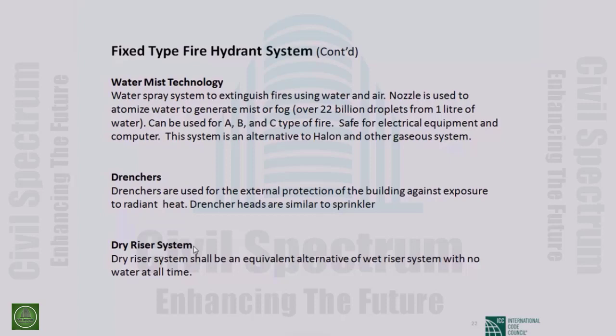So if you can keep it dry, then the pipe will last longer, the life of the system will be longer, but there will be a time gap to start and finish. So if you can properly handle it, a dry system can work, and it is very good for longer life, very long life. Normally, a hydrant system does not last very long. Within 10 or 15 years, you can see most of the valves and the engine parts are corroded, particularly in our country. So if you use a dry system, then it will last much longer. So you have to be careful with the dry riser system.